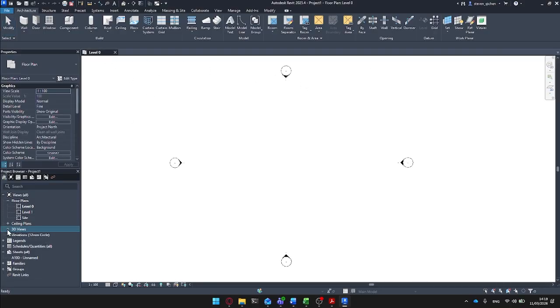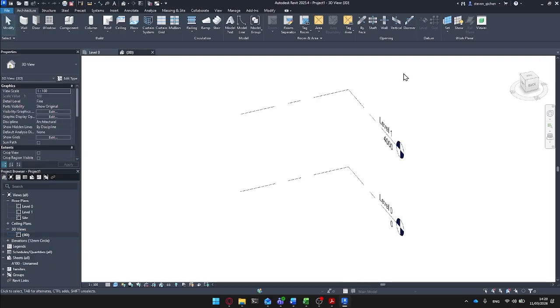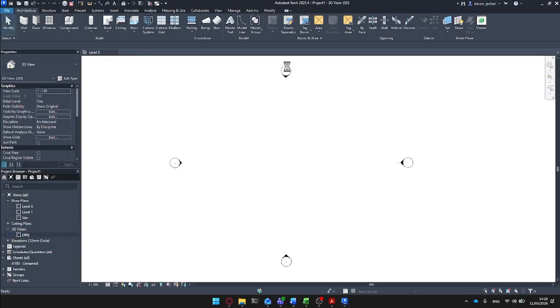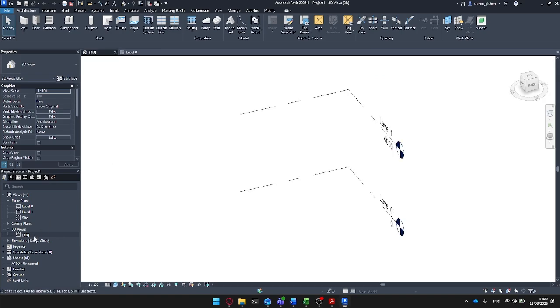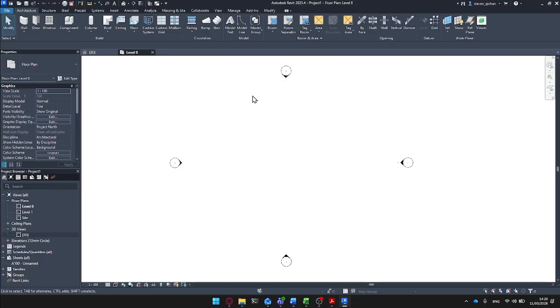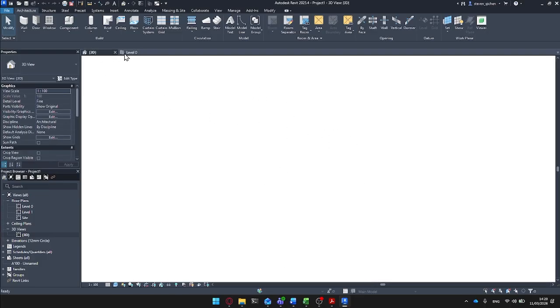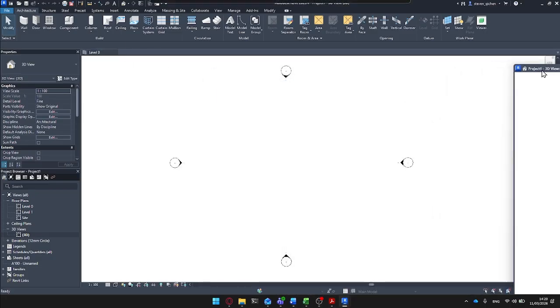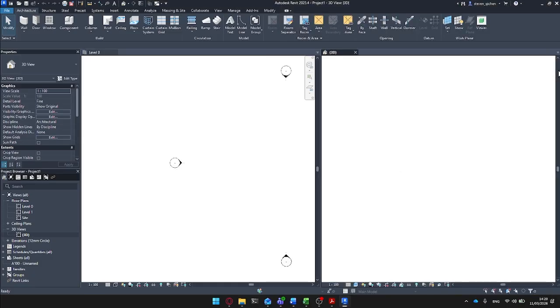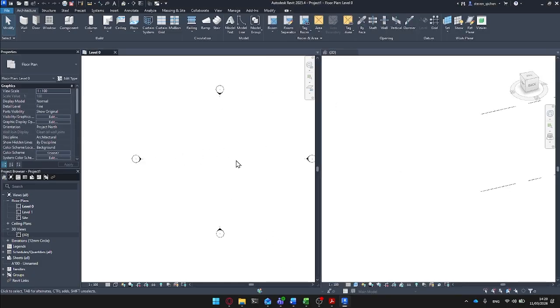And what I'm going to do, and this is my preference working on most Revit files, is you always open up into the main floor plan view. I would usually open up the default 3D view as well. And you can actually drag and drop this to the right. It's a bit finicky. And nest that like this. A bit like how you have your windows organized on Rhino.